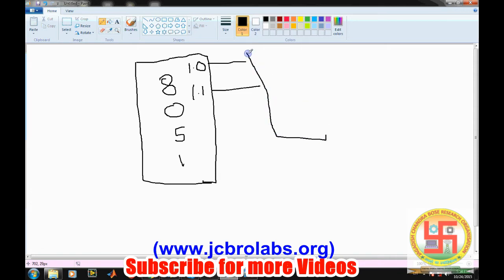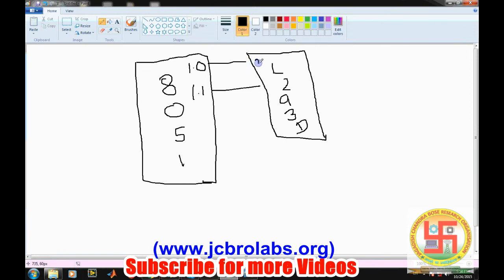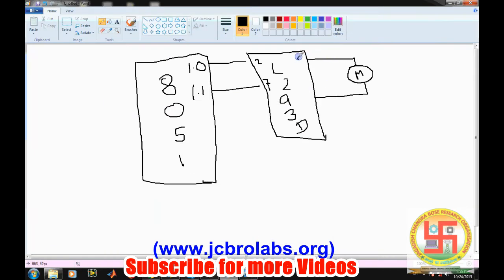These will be connected to the driver L293D IC, at pin number 2 and pin number 7 of the driver IC, and then we will connect the motor, which needs to be connected to pin number 3 and pin number 6.